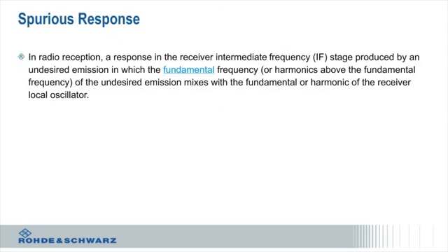Okay, so that's enough on noise figure. So the next thing one might want to consider, in a receiver, is what we call spurious response. In a receiver, or when you're looking at reception of a signal, the front end typically takes the signal and moves it down to a lower frequency signal. You'll find that's typically done by a thing called a mixer. You'll see that in a couple slides ahead, but that mixer puts out spurs, or unwanted signals, that we need to be aware of.